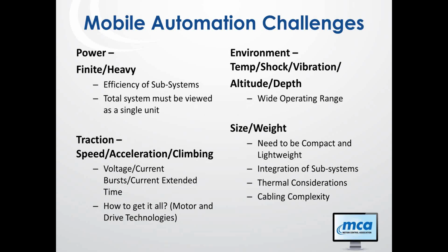So a servo drive and a servo motor need to be looked at together, and how does that effectively operate? Again, you add a gearbox in. Is there a better way that you can direct drive that? You have to look at the whole system overall. If you just look at each subcomponent, you're going to potentially not achieve the results that you're looking for.